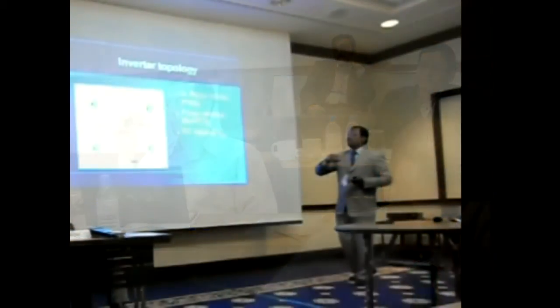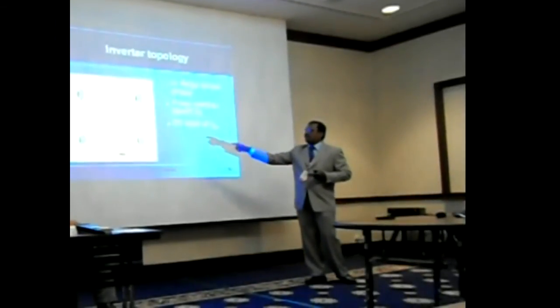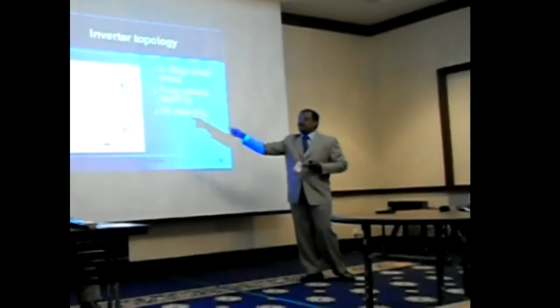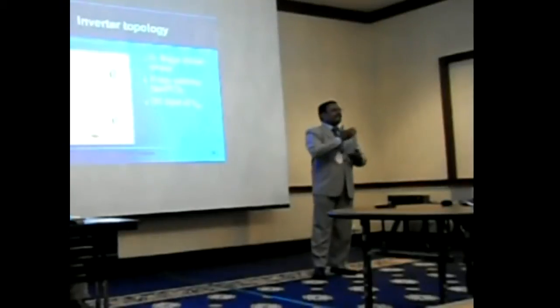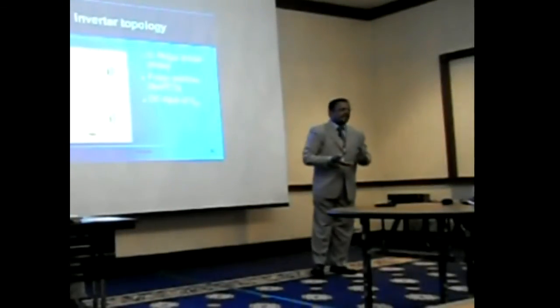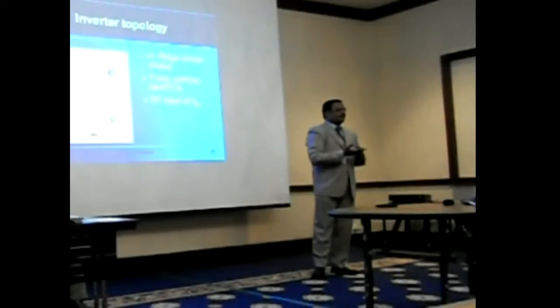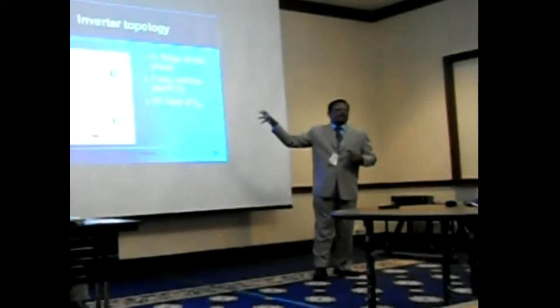This is a standard bridge for converting the DC into AC. Whenever switches S1 and S4 are closed, current flows through the load in one direction. Changing the switches to S3 and S2, current flows in the opposite direction. So getting the negative half cycle is not an issue of the shape, because when you talk about raising or squaring the sine wave, all negative components will become positive. But here it is possible to get the negatives because of the switching.